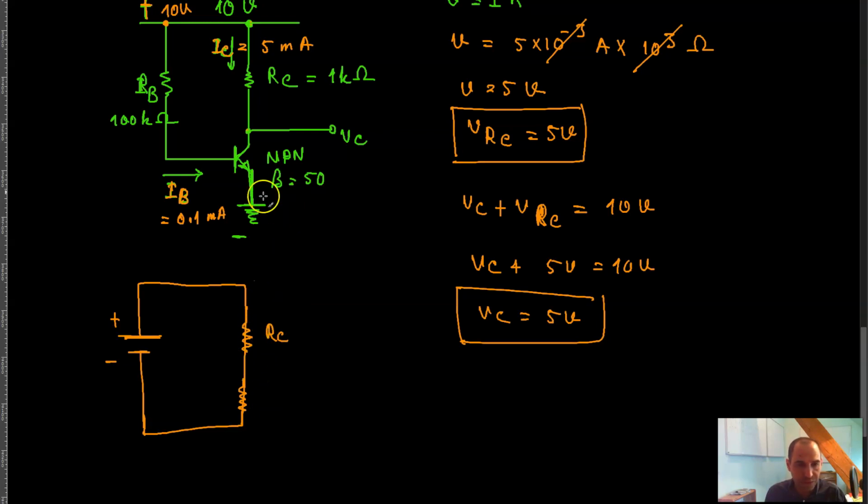and basically what that means is that I have the possibility to control the voltage drop across this resistor here using the values that I have here, for example, by changing the values of R of B, R of C, and the beta of the transistor, meaning that you take some other transistor with another beta value.